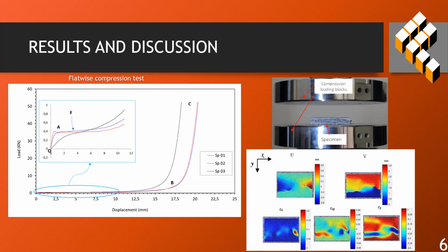The load displacement curves obtained from flatwise compression tests on the sandwich structures exhibit a consistent behavior. Initially, an elastic region is observed, followed by a plateau phase where the foam begins to compress, and finally a densification phase characterized by a sharp increase in load with minimal displacement.